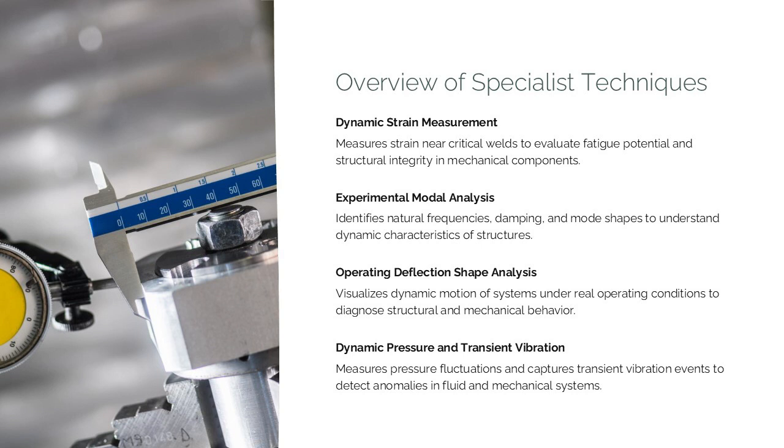Modal analysis identifies natural frequencies, damping, and mode shapes. ODS analysis visualizes the dynamic motion of systems under operating conditions. Pulsation measurement quantifies pressure fluctuations in fluid systems, and transient vibration measurement captures short-lived events through continuous data recording.